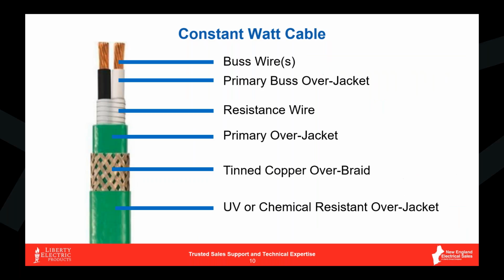copper or stainless, testing lines, things like that, the overall width of the constant wattage cable is easier to install than a self-regulating cable is. So this really becomes a little bit more of a consult your professional rep like us until you get a better feel for exactly what cable you can put on what pipe.